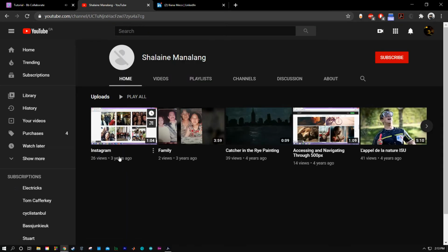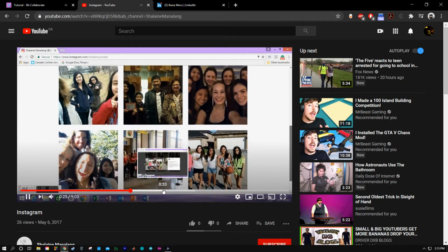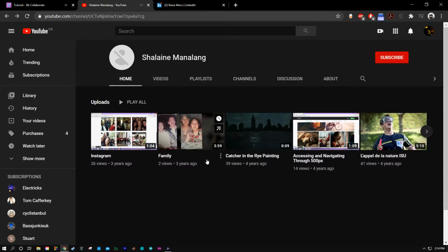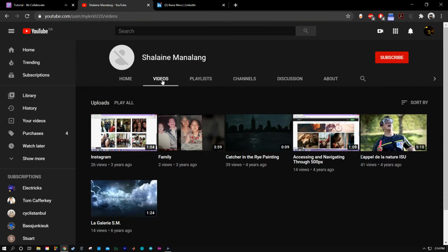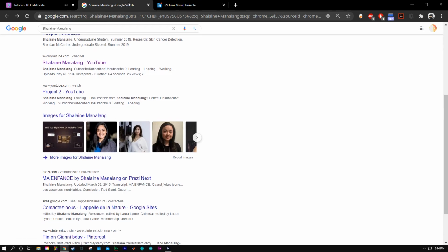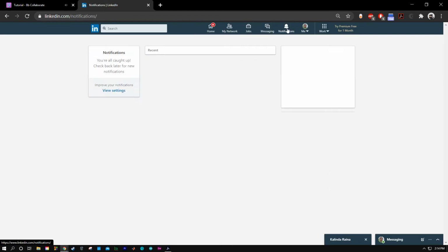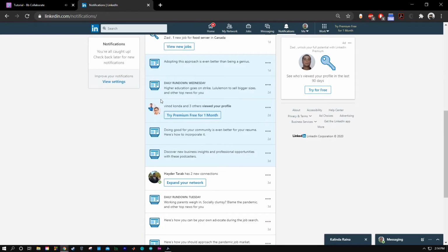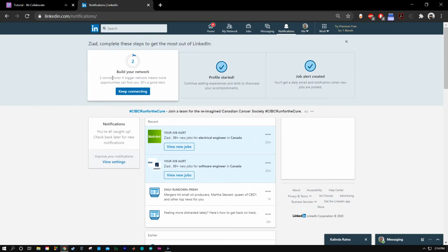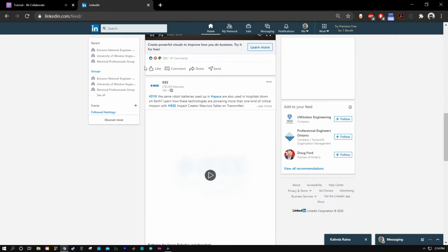So what happened was, when I do KVL, KVL states that in any closed loop, the sum of the voltage is 0. So that means in this closed circular loop here in the middle, the sum of the voltages must be 0. What are the voltages? There's a voltage drop across this resistor right here, the 2 ohm. There's a voltage drop across the 4. And there is this voltage source right here. There's 3 voltages we can consider either as drops or sources.